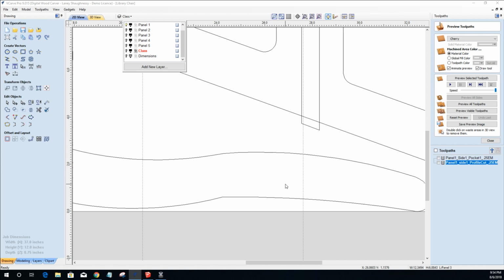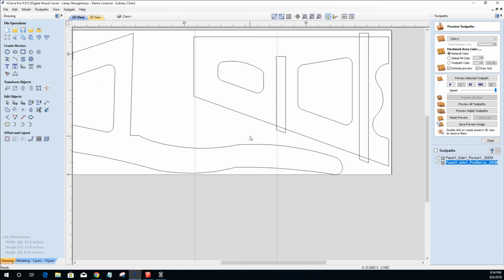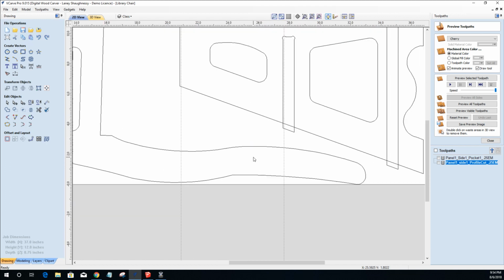If you're doing this out of oak or something, 1/4 inch oak dowel, or you can have your CNC cut little 1/4 inch plugs. Personally, from Harbor Freight, I have a plug cutting set that has a matching countersink, so I can countersink my holes. I'm going to have the holes in here where you would normally put the back, but it's going to be for my size back. If your back is longer or taller and it takes up the whole thing, then your holes are going to be in 2 different places. But I'll have the holes in there.